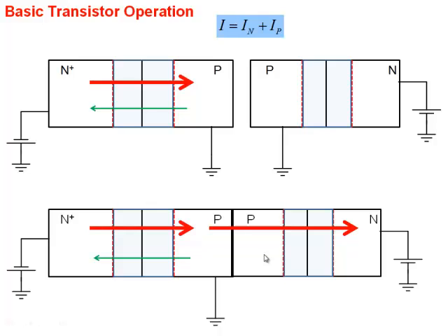Width of the collector can be less, can be more, doesn't matter. Why? Yeah, but you see the electrons that are here, they come over to the collector side. Collector is anyway n-type. After that it's like a resistor, and they get collected. That's all.